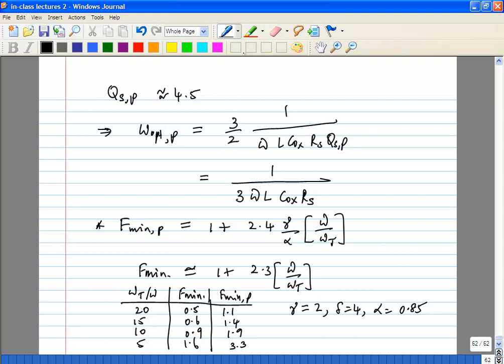Why would CGS increase if you increase power? Let's say you take a given size, and you burn, let's say, 1 milliamp of current in a 10 micron by 0.13 device. It has a certain Gm, a certain CGS, and a certain omega t. Double the current to 2 milliamps, what happens? Gm goes up, whereas CGS stays the same. So omega t will automatically get better. So when they talk about omega t for a particular process, what they are talking about is for a given size and given current consumption and so on.